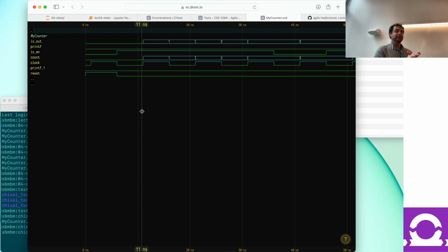That'd be appreciated. But yeah, like I said, if you're working, for example, on the labs in Binder, you can download your VCD file and then drag it into this browser window to get that web version. But this is more important for the homework, where we have bigger, longer, harder problems. There, you should definitely figure out a way to get waveforms going. GTK Wave, the one for WaveTrace in VS Code, Scansion, whatever you're using.